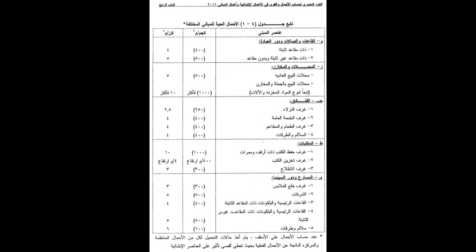The live load for the workshop must use the actual weight of the equipment or machines, considering the vibration effect, adding dynamic factors. This can come from the machine manufacturer.